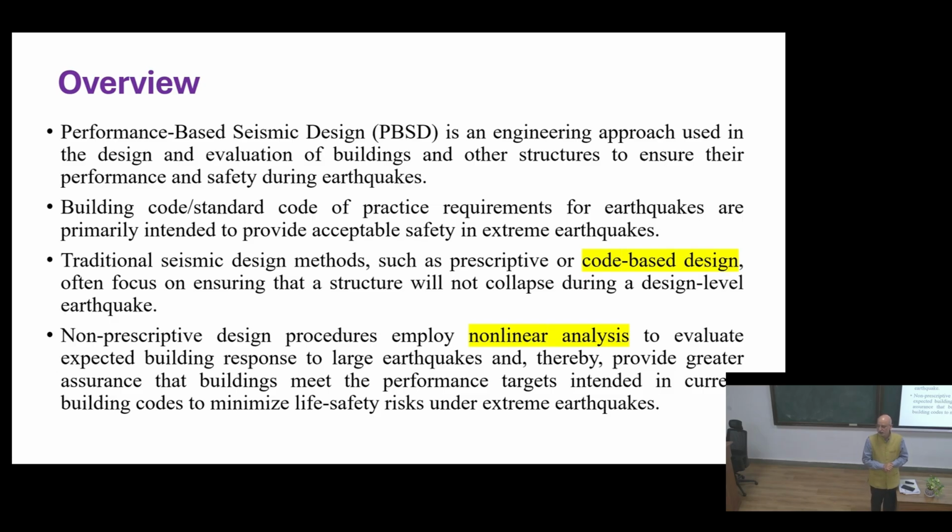So when we're doing it, the very point which is mentioned is that the structure will not collapse at the design level of earthquake. Now there is a certain level of earthquake. As a common person we talk about, as far as our country is concerned, we divide it into 5 zones. The first zone we don't consider a seismic zone, but for the remaining zones we design the structure. Zone 5 is the highest level, where the northeast region, part of Jammu Kashmir, and part of Maharashtra also fall within that range.